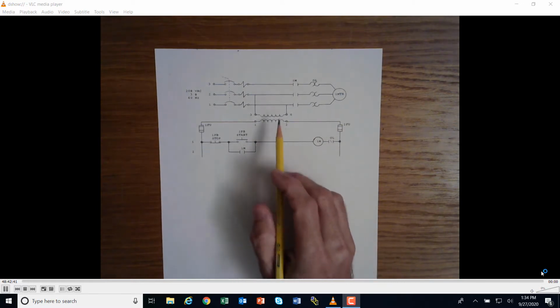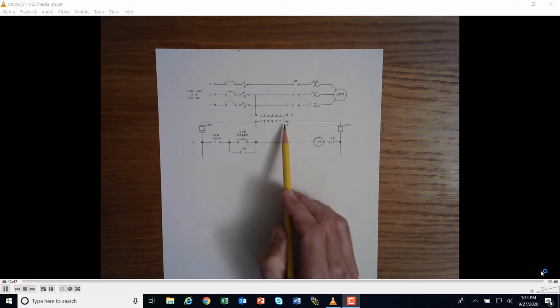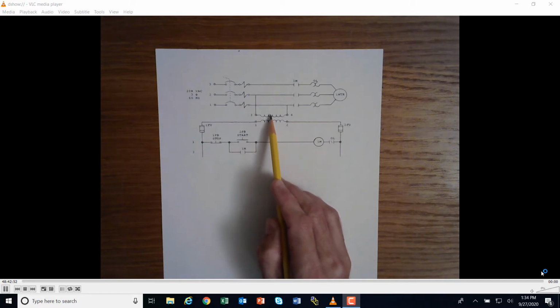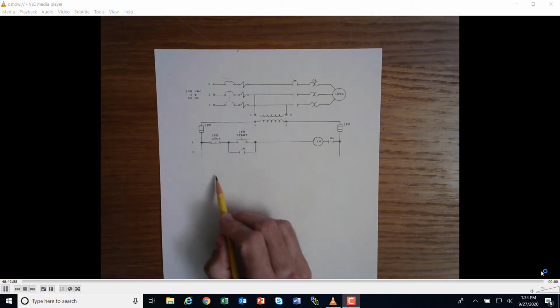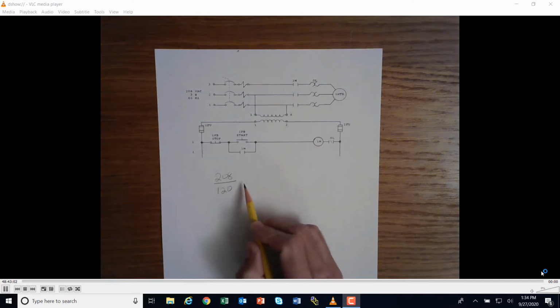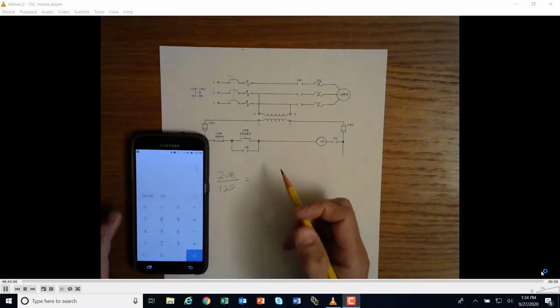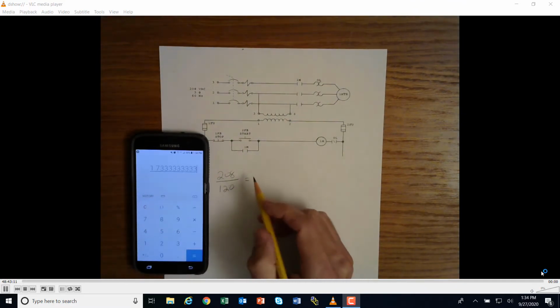So the first thing to recognize is that this is a center tap transformer. This is the Lab-Volt transformer right here. That's what that's showing. It's not the industrial control transformer where you put it in series and parallel. It's just you pick off the center tap that you want. And what this did is this provides 208 on the primary and it provides 120 on the secondary, okay? And so if you do the ratio from 120 to 208, 208 divided by 120, you get 1.73.